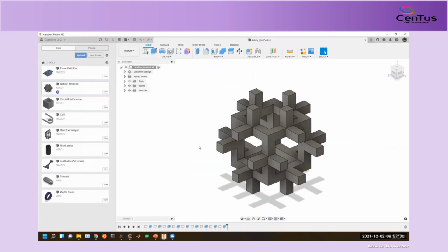So if you want it on the unit cell, what you would do is create your unit cell still in a rectangular shape, create the shape that you want, and then apply a scale factor afterwards to create your unit cell that has some sort of squish or deformation to it. And that way, whatever your unit cell looks like in this unit cube is what that base unit cell is going to be.